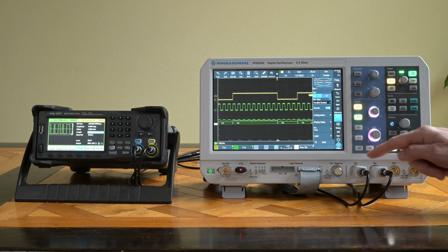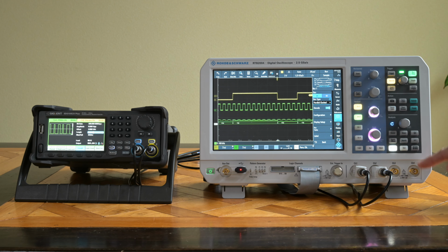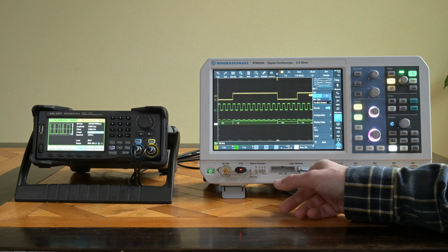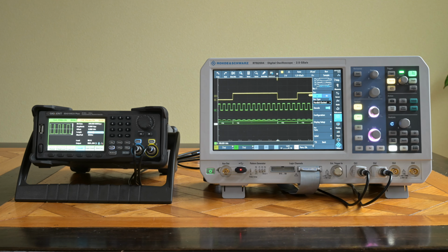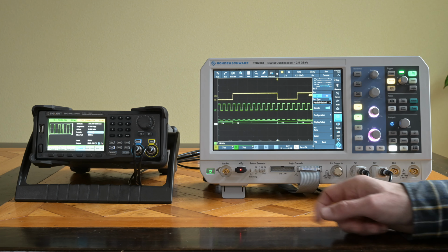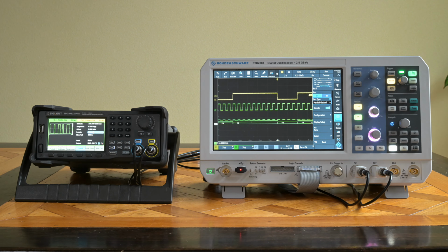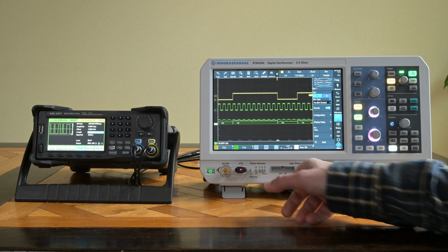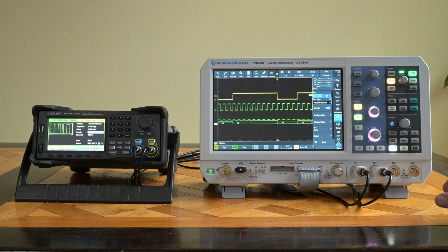It's a little bit too bad that Rohde and Schwarz did not implement this function for buses up to 4 as well, with just the analog inputs and the threshold settings, so people could do what I'm doing here today without actually having the logic channels. But this is only possible, and you only get to see it in the menu, if you're digital. Actually, when I was trying to do this yesterday, I just couldn't find that function anymore, and I thought it was removed with a firmware update or so, but of course that was not the case. I just didn't have the digital interface activated, so it was not showing up in the menu.